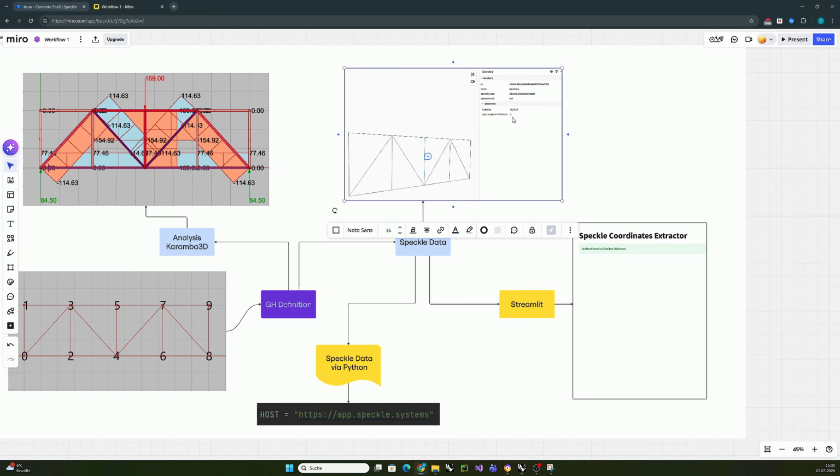Now I want to make a step into structural analysis, but first I want to be able to mirror these diagonals. These were my curves B. Let's just grab, we want to mirror the geometry and we want to have the original curves. Around which plane? We need the curve middle.